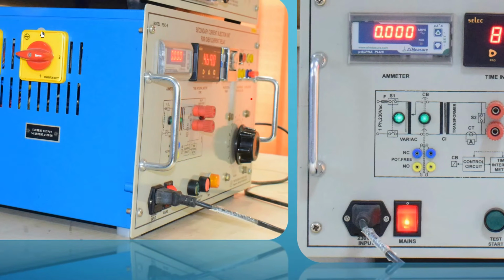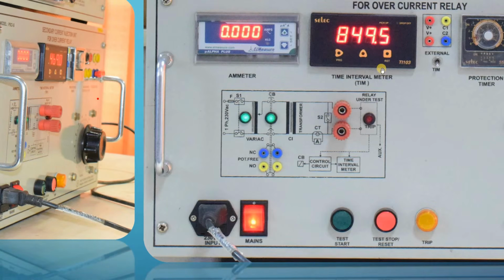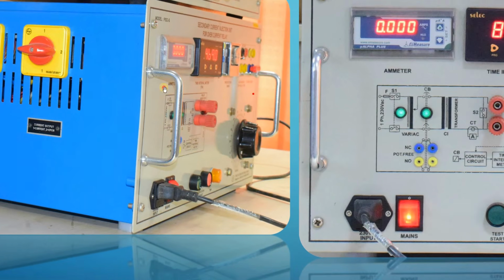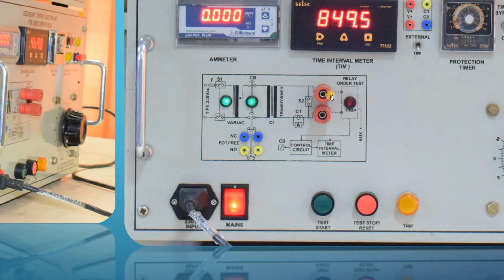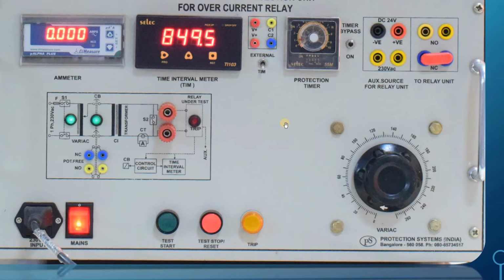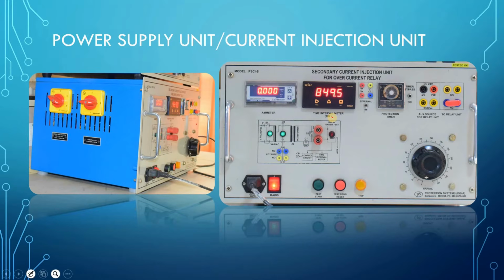You can see that the function of this switch is to allow current to the relay or not. This other switch decides how much current we can apply from the current injection unit. At position 1 this unit can supply a maximum of 1 ampere, position 2 is 2 ampere, position 3 can supply 5 ampere, and similarly position 6 is 50 ampere. That is the full scale output capacity of the current injection unit. So this is studied. Next we will see.